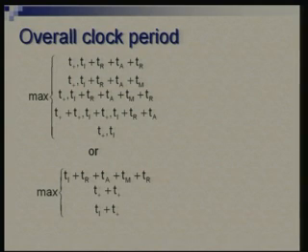Now looking at all these together, some things can be thrown off because there are other things which are clearly dominating those. So T plus alone can be thrown off because there is a T plus plus T plus. The long expression we have for load word LW dominates the big expression we had for add, subtract, and also the one we had for store word. So this reduces without any assumption to the bottom expression where it is max of three of these expressions. The first one is coming from load word and the next two are coming from BEQ, right?